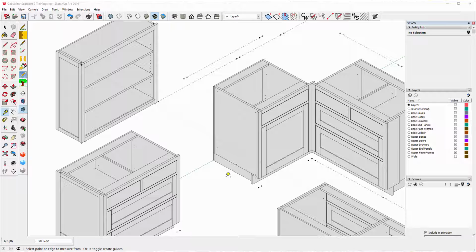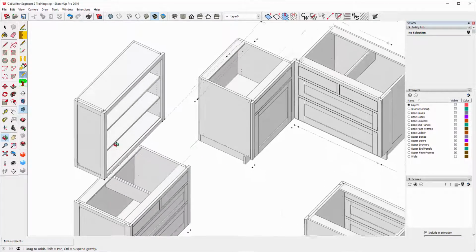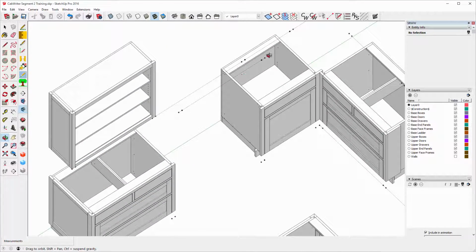Now, the refrigerator cabinet, I'm going to rotate around here a little bit. The refrigerator cabinet is right here. The height of this cabinet is dependent on the refrigerator's height. Its depth is also dependent on the refrigerator. The actual, what I should call the height of the cabinet is not this, but this is where the cabinet begins. It begins a little bit above the refrigerator. In this case, I believe it's 71 inches. The height of a refrigerator cabinet is going to be 24 inches, and its depth 26. And all of that is dependent on the refrigerator itself.